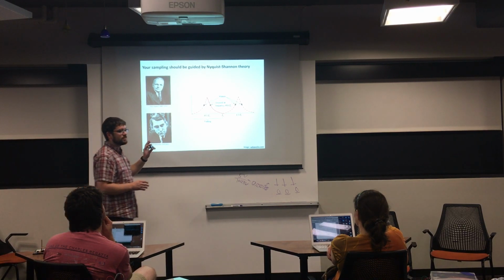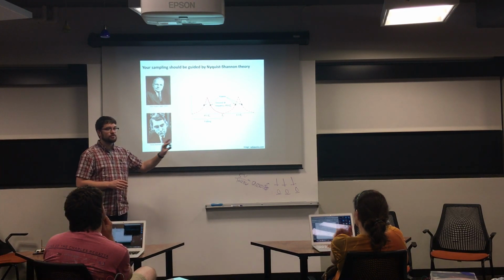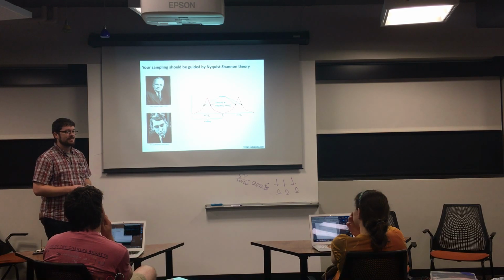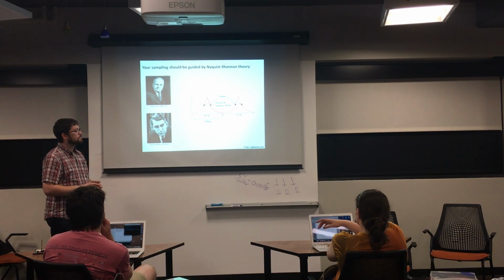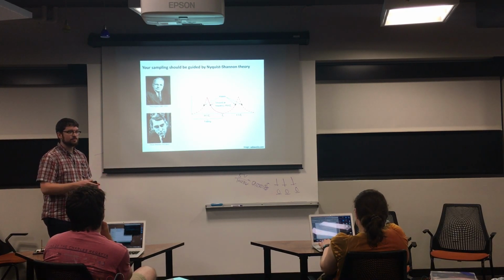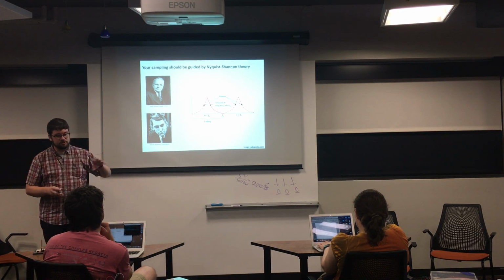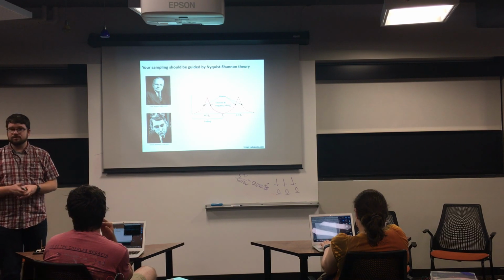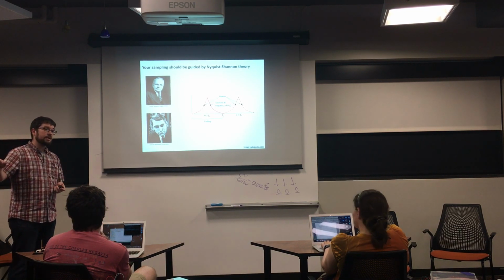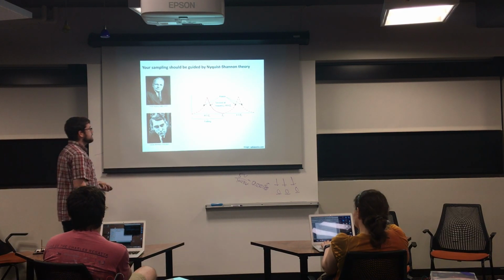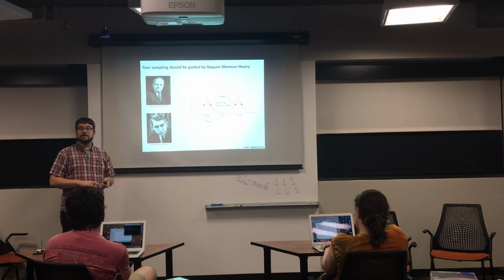Generally, as a rule, I would say you always want to sample northwards of 2 or 3 times that, more if you can, and you can always downsample later in your post-processing. But the bad thing about this is if you do alias data, so if you've got a higher frequency signal, even if you don't care about it, it will be aliased into your data, and you'll have no way to know it's there or to hear of it.